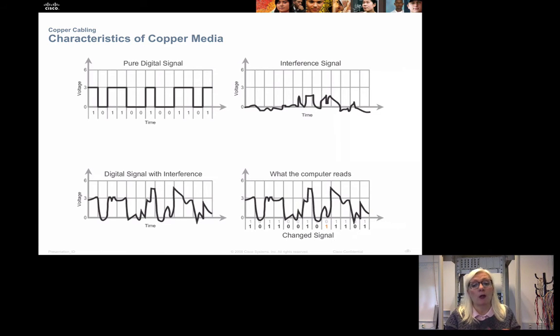properties of a copper cable, we will see that the signals are sent as some kind of voltage or no voltage, high level of voltage to a lower level of voltage, but it is sent by current and voltage through a copper media. This means that it could be influenced from the outside, and we have different types of interference. It could be other cables, it could be just current running through a power cable, it could be other types of devices which emit electromagnetic interference, or EMI.